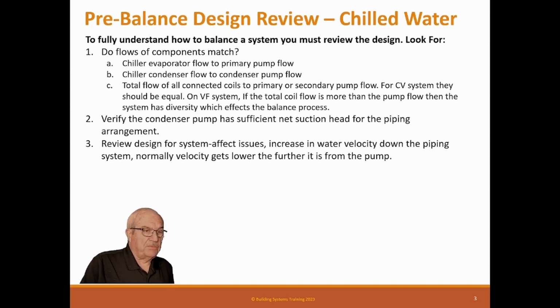And remember, system effect is where we require to increase the velocity of the water, and that takes horsepower. So we want to avoid that. You can go from high velocity to low velocity for free. It does that by itself, but you can't do the other way around without using horsepower.